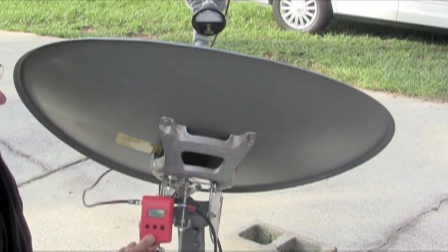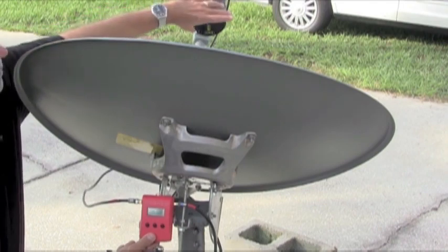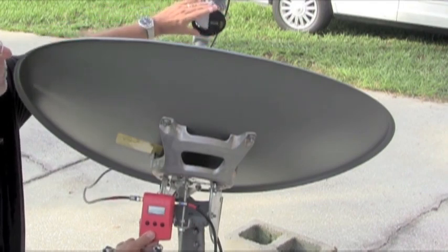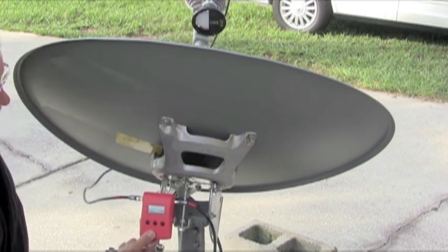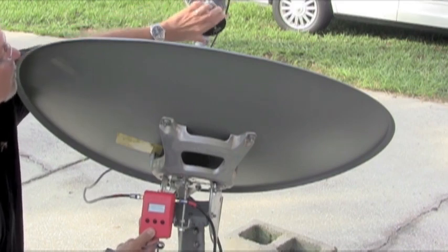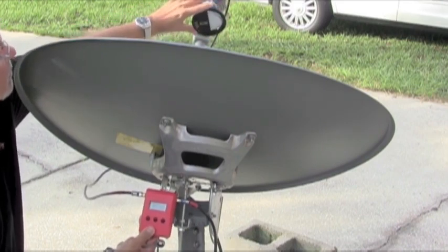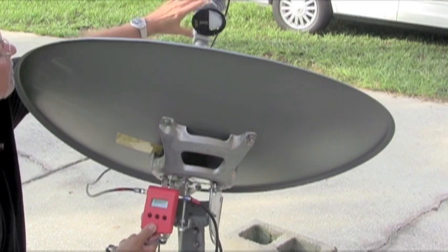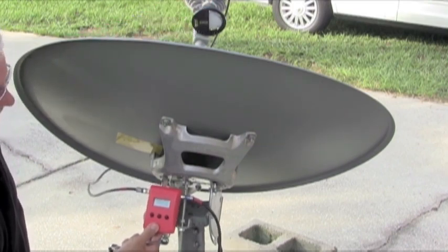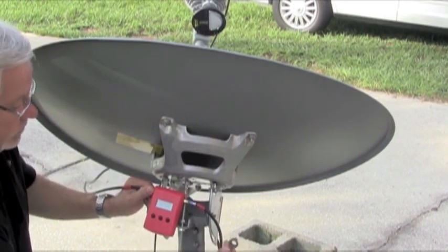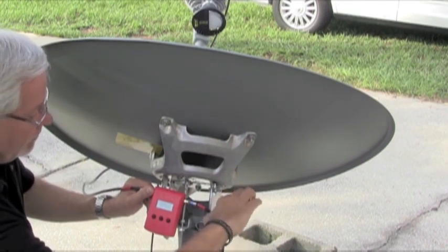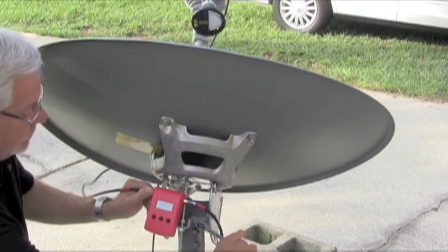Now, one final test, we're going to check the azimuth again, because whenever you make an adjustment to a dish with a tilt angle involved, whenever you adjust either elevation or azimuth, it affects the other. So we should always double check it. And we can see that value is just a little bit higher, so it did have an effect on it when we adjusted the elevation. So now we can see just a small adjustment needs to be made on azimuth. And basically what we're doing is we're narrowing down to the center of the beam. It might take a couple adjustments on each side.